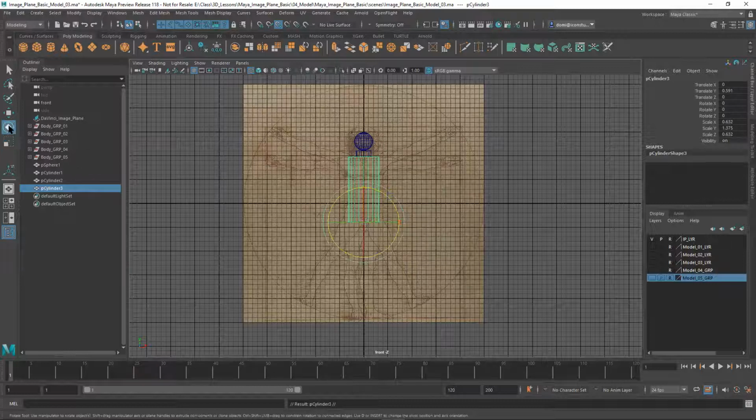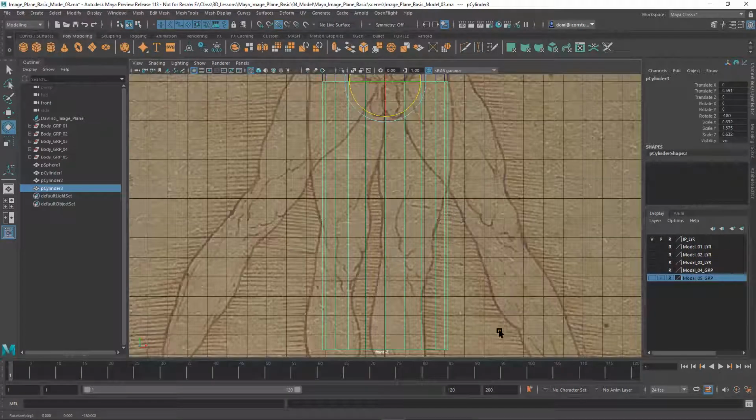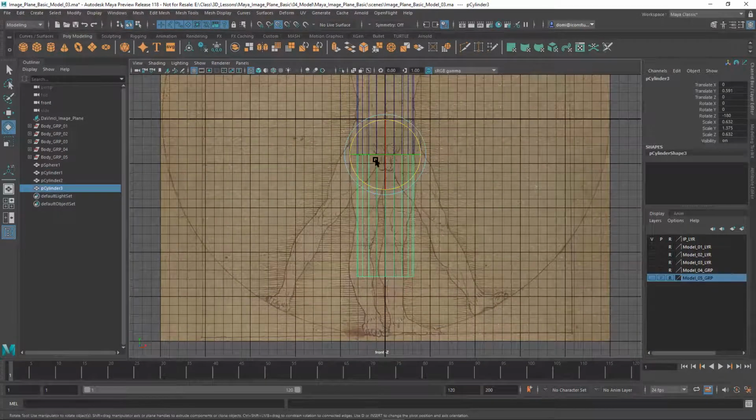Now I'm going to rotate it. Okay. While we're at it, I can show you a trick. If you hold the J key, your rotations now will go on in 15-degree increments. So you might want to try that out. That's kind of fun. Okay. So now I'm going to hit the F key for zooming in on it. I'm going to zoom out a little bit. So now I want to move it over.